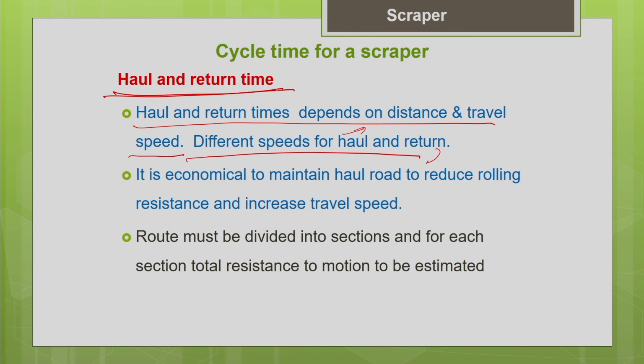Whatever efforts you are putting in to maintain your haul route, it will help in reducing the cycle time of your machine. It will help in reducing the haul and return time, and that way it will improve the productivity of your machine. So, it is economical to maintain the haul route.